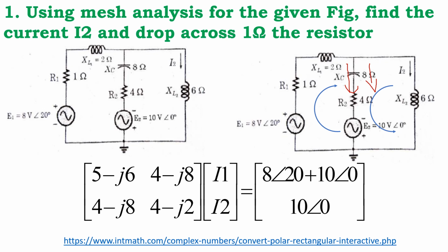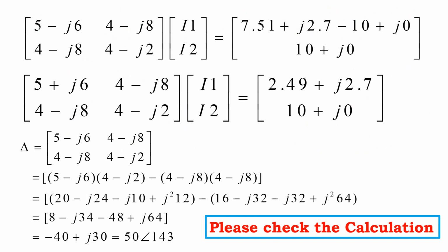Once the matrix is constructed, we can go for the calculations as we discussed in the previous video. So we got this matrix. First, simplify all the equations. I simplified this equation, so please check the calculations also using a calculator. Now I got this Z matrix, I matrix and V matrix. I converted from rectangular to polar to rectangular first, then I got it in the rectangular format.